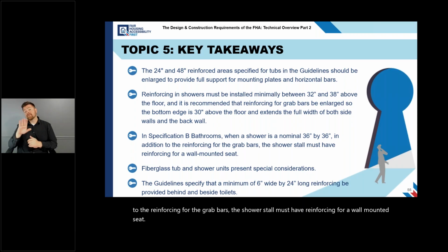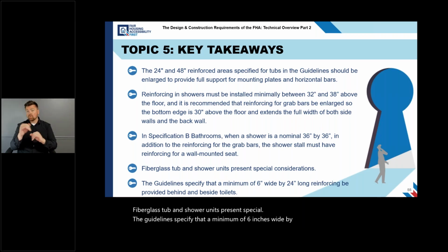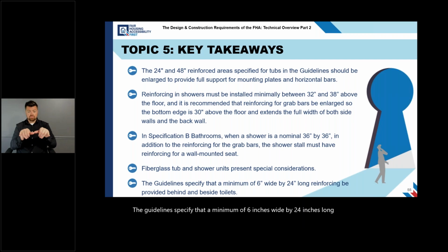Fiberglass tub and shower units present special considerations. The guidelines specify that a minimum of 6 inches wide by 24 inches long reinforcing be provided behind and beside toilets.